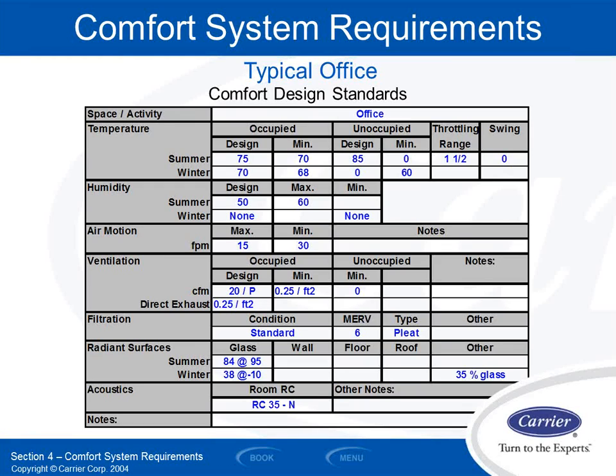So if it's a 0-degree day outside and 70 inside, it's a 70-degree delta T. Heat moves from my inside to outside at a certain rate. If I lower your set point from 70 down to 60, now it's only a 60-degree delta T. So the heat moves at a much slower rate out of my building. So generally, if I go into setback mode and my temperatures inside are a little bit closer to my temperatures outside, then I don't lose heat as fast.